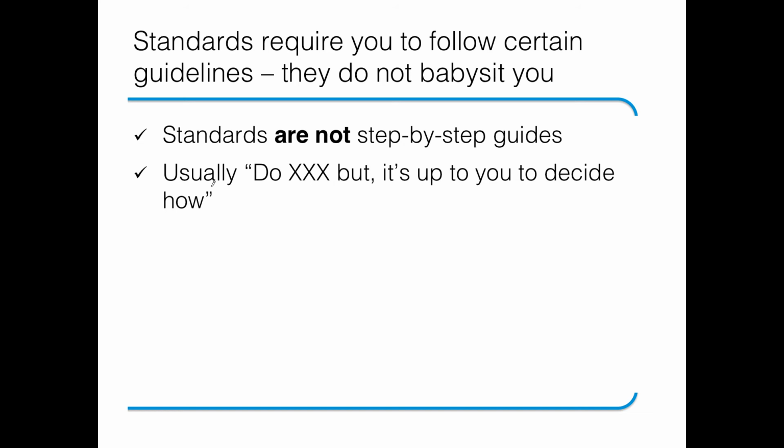And if we take another example, from the standard EN 1090-1 that deals with the general FPC system, there's a requirement for the personnel that you must have a personnel listing that includes the relevant experience that the employees have. You must record the relevant experience and the expertise that is related to their work.